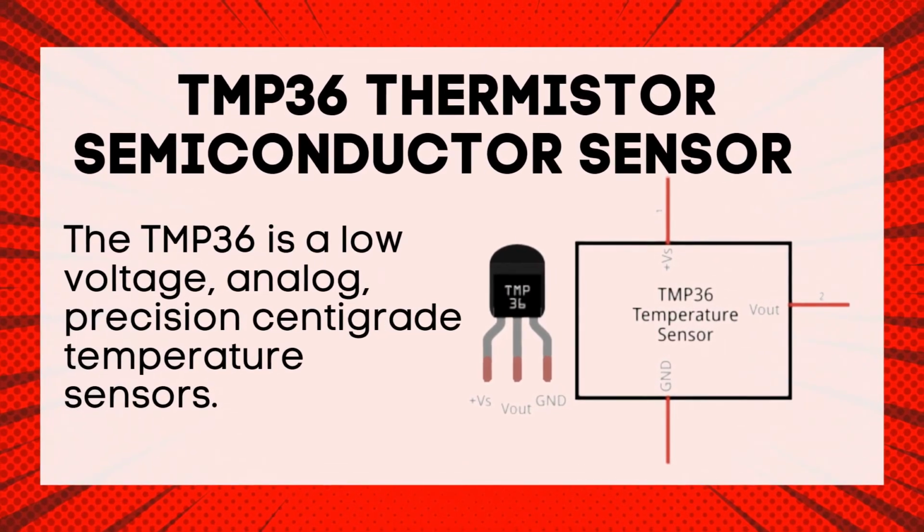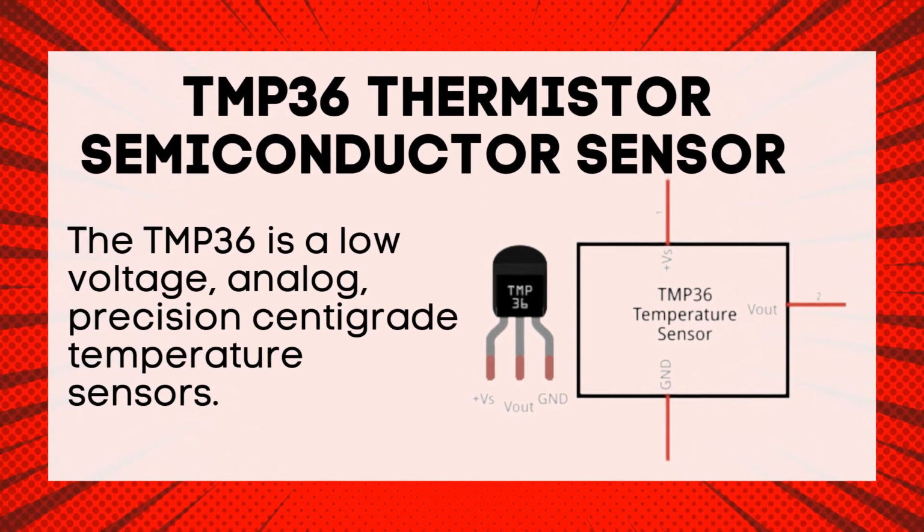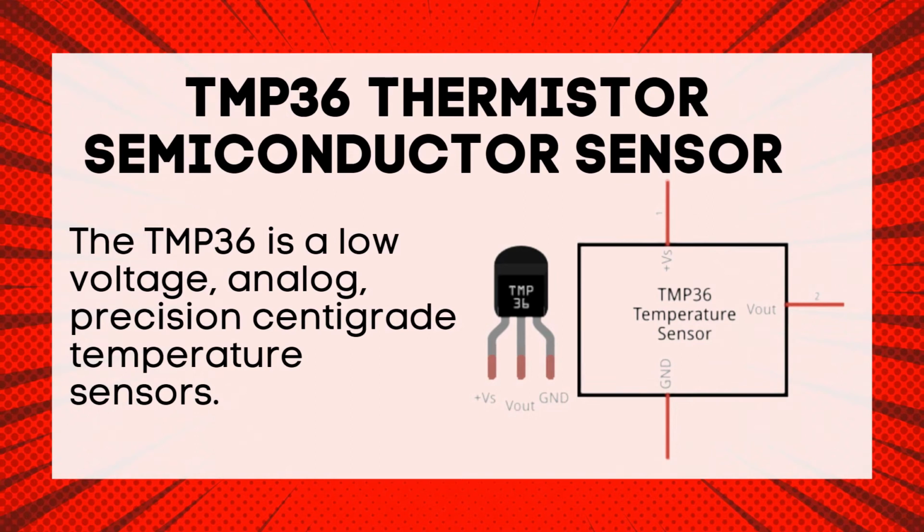So, let's have our activity. Let's talk about the digital thermometer. In this, we're going to learn how to make a computer-based thermometer that can sense and record ambient temperature. Our activity will help you create temperature monitoring equipment using the TMP36 sensor. The TMP36 sensor is a low voltage analog precision centigrade temperature sensor. The ambient temperature readings will be displayed on your computer using the serial monitor function of the Arduino IDE.